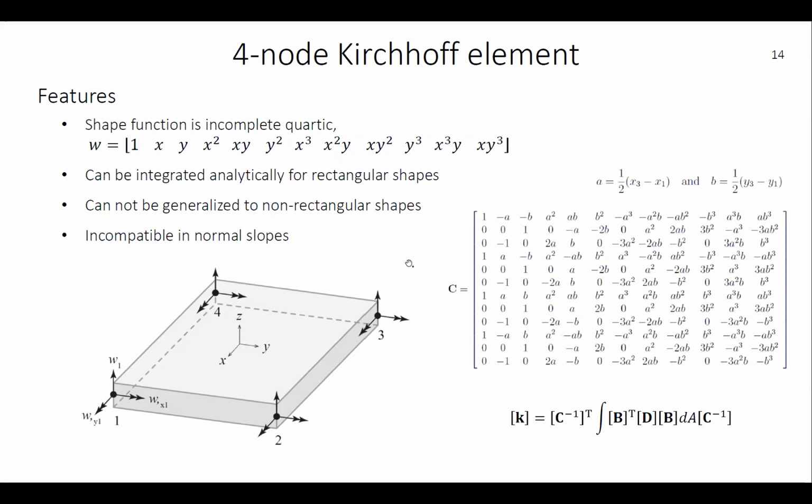There are a lot of different element formulations for plates, and usually what you would see in commercial software are shell elements, because you include the membrane components as well in the same element. So there are not so many pure plate elements, I imagine. But I will go through shell theory in the next lecture next week. So for now, we're only looking at the bending components.